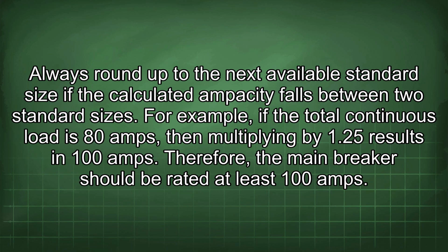Always round up to the next available standard size if the calculated ampacity falls between two standard sizes.